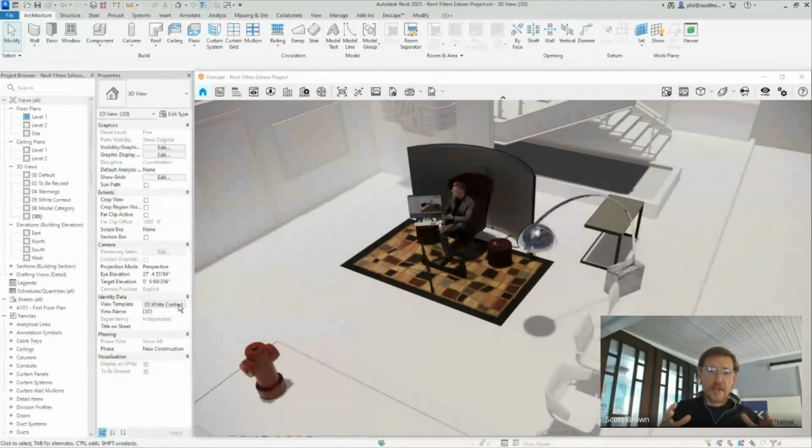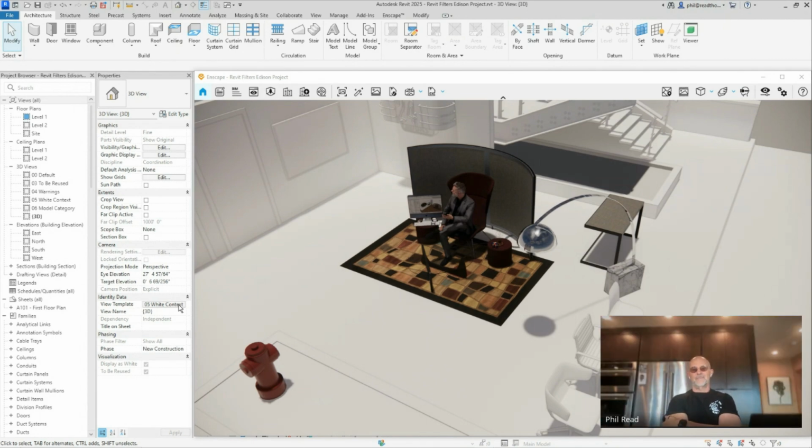Cool. Yeah. That filter box, if people don't know, I did mine different. I wanted to save my normal view template that I use for my coordination or quality control view in 3D. And I just made a whole bunch of filters that I'd want to cycle through. And now that Revit has that enable filter button, you can just have all your filters there instead of switching from view template to view template, which is totally cool. I like that. You could just have a group of filters for QA/QC in Enscape. Oh, nice. Have them disabled.